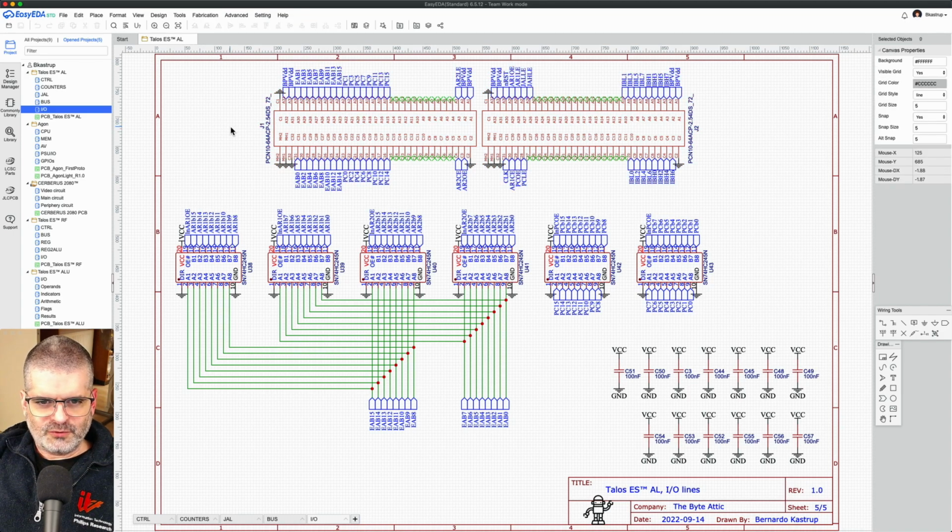But for this one, we have a dedicated space, and the reason is there are 2 address buses that need to go out to the motherboard. The PC bus, program counter, and the external address bus. And that's 32 signals, and I counted the available pins on the backplane connectors I chose, and there wouldn't be enough if I would make everything dedicated to only one signal. So I'm reusing here the lines that were used between the register file and the ALU for them to talk to one another around the buses without using the buses.